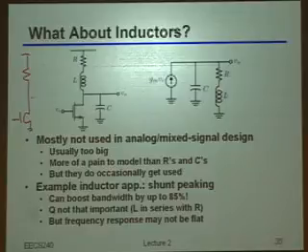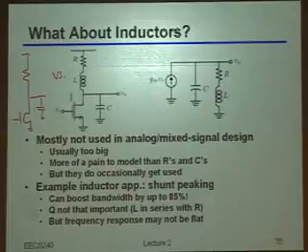So let's say I take this amplifier that I just drew in red on the left, and I compare it against this very similar amplifier that has this inductor added into it. Turns out this idea of shunt peaking is that if I really choose the value of this inductor appropriately, for the exact same bias current in this amplifier as in this amplifier, I can in principle at least make the bandwidth of this amplifier approximately up to about 85% or so higher than this amplifier. And again, for the exact same power dissipation.